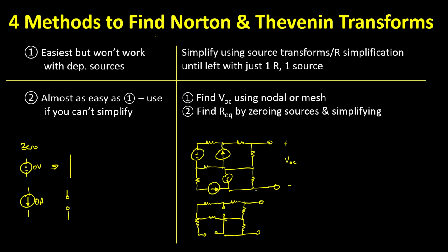To determine what resistors are in series or parallel, it's easiest to visualize if we push current into the top and extract it from the bottom, and ask what pathways it can flow through. And I see those three pathways. And that should start to tell us what resistors are in series or parallel. So for instance, I can see that for these three resistors, all the current that goes to this first resistor has to go through the second resistor, has to go through the third resistor, so therefore those three resistors are in series. And so we can simplify the circuit.